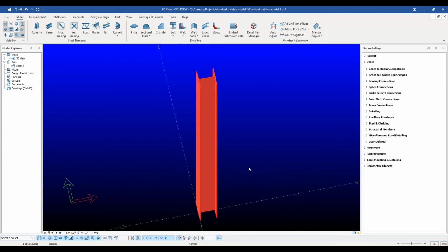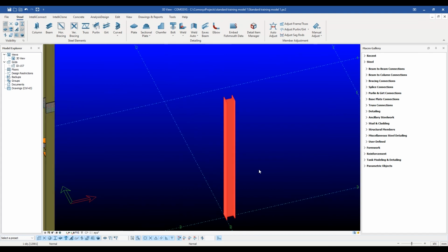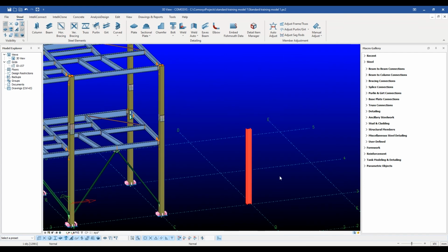Similarly, the position in depth and position in plane anchors can be modified by using Ctrl W and Ctrl E shortcuts repeatedly. Since anchoring the section is one of the most frequently performed tasks in 3D modeling, these shortcuts greatly reduce the task of the modeler.